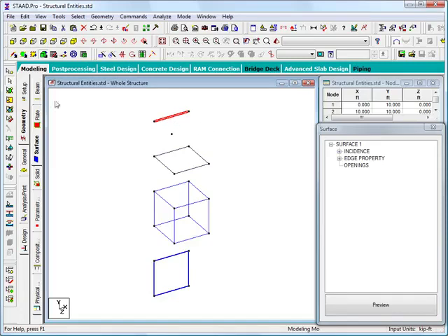The second item that we can work with, or entity that we can model with in Staad.Pro, is a node. And so I'll use the nodes cursor here to highlight a single node in this model. Very simply, nodes are just points of connectivity between other structural entities. We'll sometimes use the term joint and node synonymously, and nodes can be selected in Staad.Pro either by the nodes cursor or by this geometry cursor that's a catch-all.